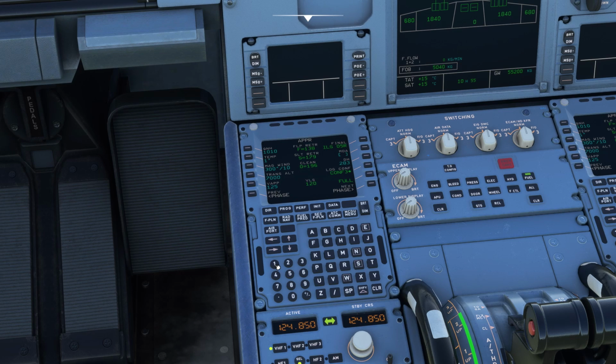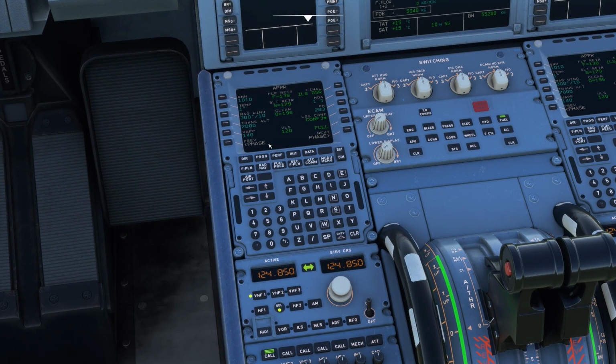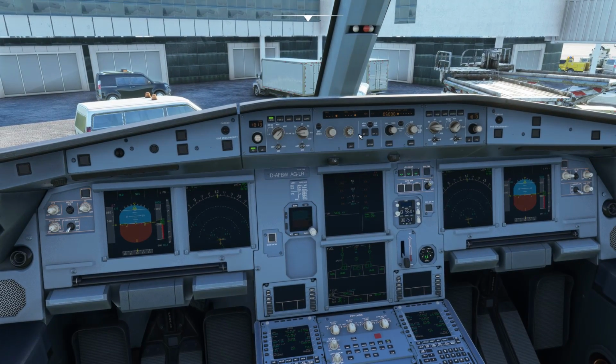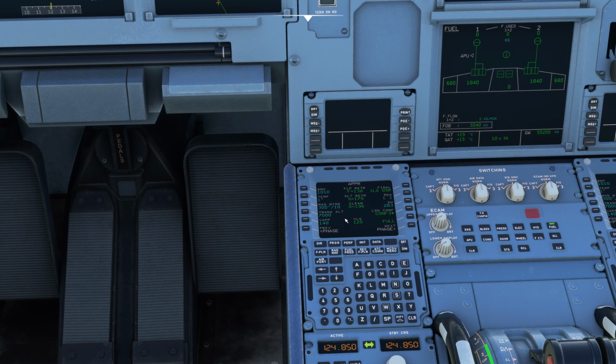Now 125, that's a little slow for me. I normally like to land at about 140 in game, so I'm going to enter 140 in there. Now that should mean that when I've got the flaps to full, the aircraft should be kept at the speed of 140. That's if I've got speed as managed speed. If I had it as selected speed, it would be to whatever I select. Okay, so that's that done.